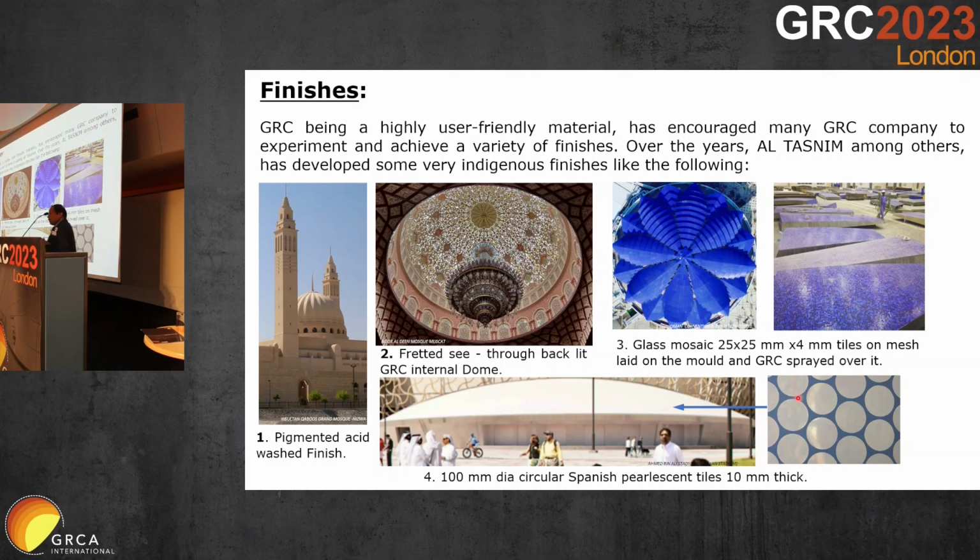Ultimately, even after casting, we tested with a rubber mallet and checked whether any hollow sound was coming or any popping of the tile. But no, not a single tile came out. This project is now almost 7-8 years old. And these were the panels. You can see the size of the panels. They look tiny here, but they were huge panels.